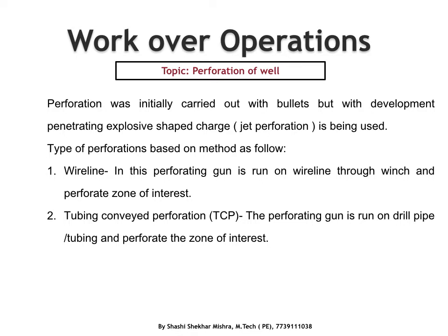In shoot and pull, after perforation we have to kill the well, and after killing we run the completion and later put it on production, which initially damages the flow index of the well due to the killing after the perforation. So TCP has more advantages, and it can also be used in overbalance perforation.